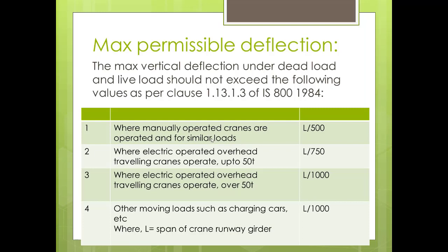This is the maximum permissible deflection. You have to check whether the actual deflection exceeds the maximum permissible deflection or not, as per the IS code. This is given in the IS code as per clause 1.13.1.3. If it is exceeding the values, then we have to redesign it.